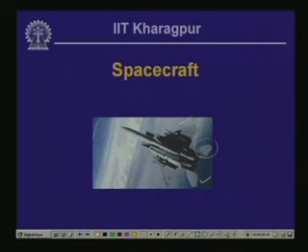And also one of the requirements of this spacecraft is that the material which we use, or the whole structural body, should be lighter in nature. Now, if we have to adhere to this condition, we need to look into a type of material which can safely withstand the forces that will be generated in this structural form. At the same time, it should not contribute much weight to the structural form. In one word, the whole structure should be stable, it should be strong enough to withstand the external forces, and it should not have excessive deformations in different positions.